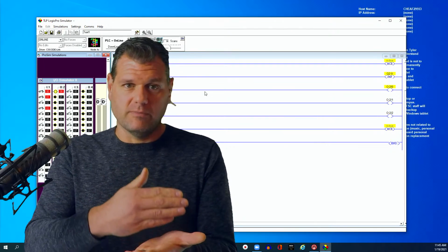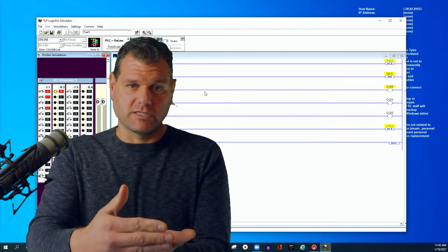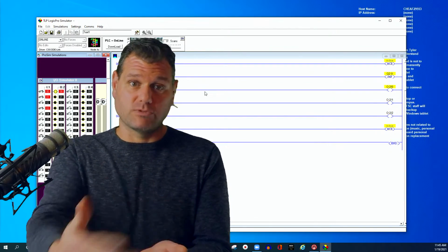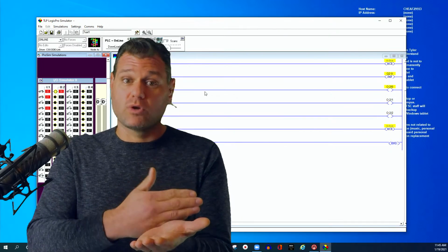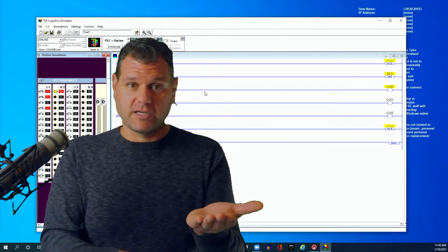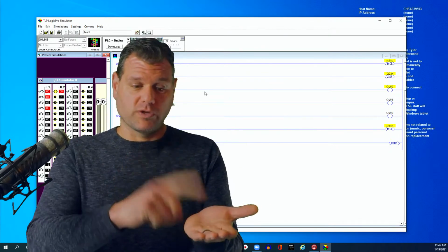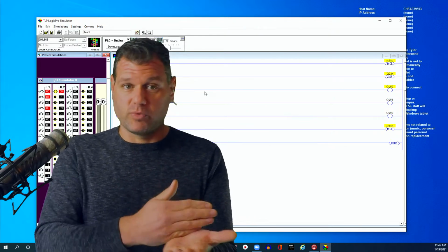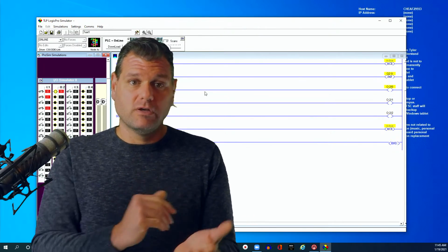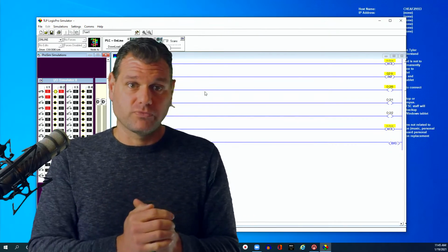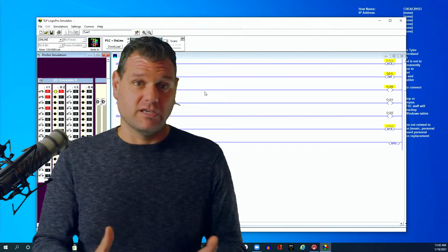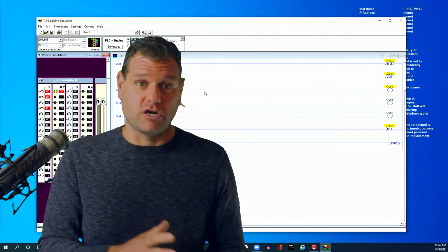When it gets to the end of its stroke, it sits there and says, stop motor, because I don't want to keep driving into something. If that's one of the conditions and you jump over that section, the motor is going to stay on regardless. If you hit that limit switch saying it's reached its end of travel, that motor is going to keep on trucking because you completely skipped over it and it never scanned it to say is the switch on or switch off.